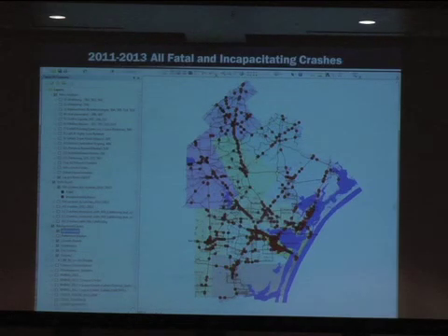Okay, then later what we did was import this information into our catalog and process the data. Then that was imported to ArcGIS. In ArcGIS, we filtered our data, then created layers for each work code. While we created the layers, we defined our symbols for each type of crash.